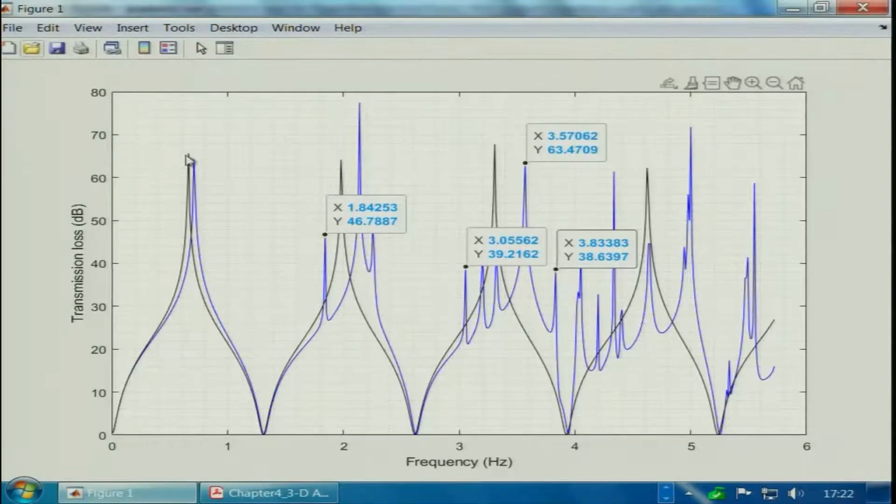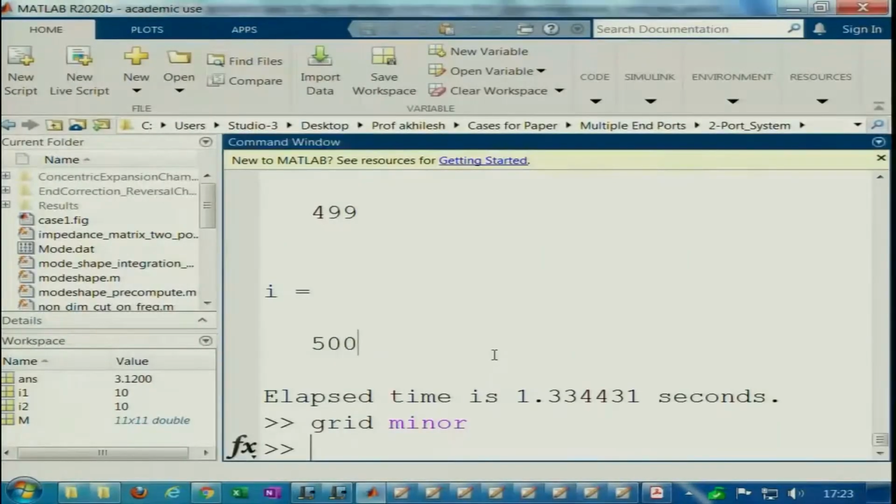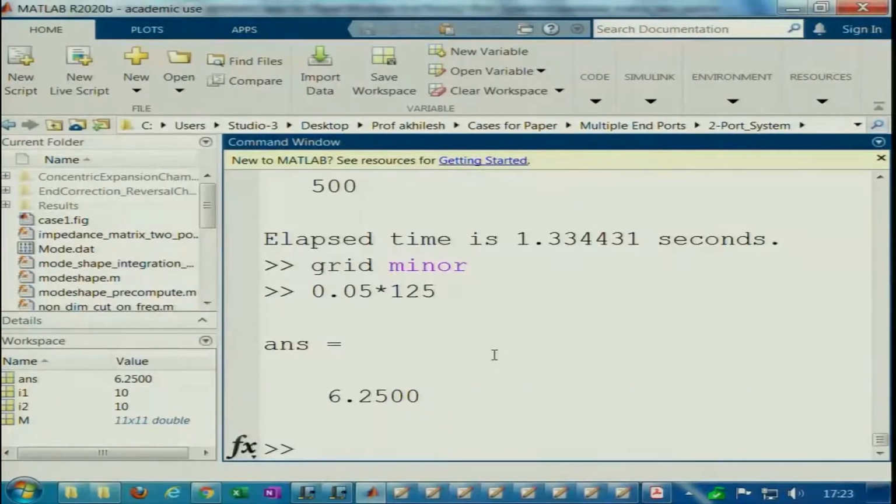You see a small shift. Based on 3D, the peak was occurring at 0.709, 0.71, k naught R naught equal to 0.71. That we can work out in frequency, and for just the plane wave it is occurring at, I guess, 0.68 or something like that, 0.66. So, there is a difference, 0.05 R naught. 0.05 into 125, if you do, well, you need to work out how much it would evaluate to in hertz, but there is a good 20-30 hertz difference in the attenuation peak.